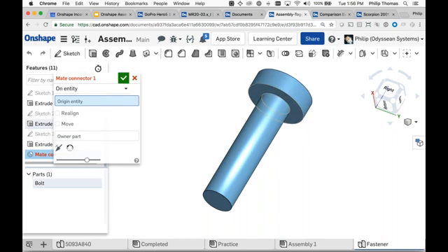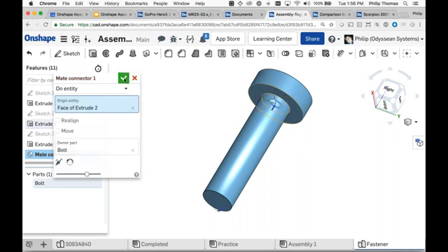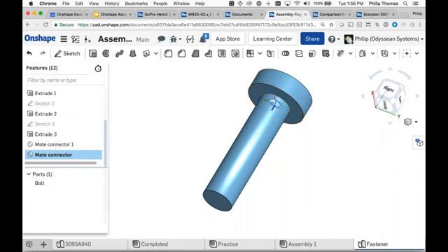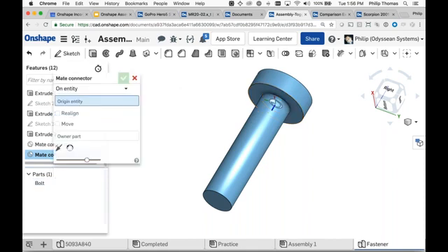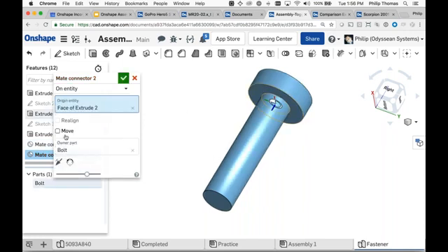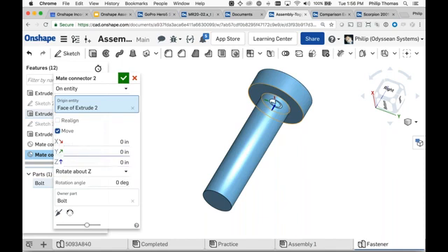So I could say I want a mate connector that's here. By the way, in SolidWorks there's that tack button that holds the dialog up. If you're transferring to Onshape and want to do the same thing, it's Shift-Enter, which duplicates it. So you can see that's the first mate connector we created. Here's another one. And I want to offset this one along Z by, say, 1/4 inch.